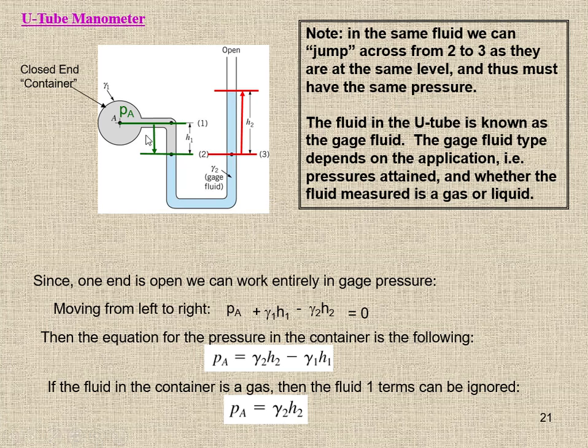The other way, we set the pressure of this side equal to the pressure of the other side. The pressure here and here is the same, so there is no use including the height of the column of this fluid, because it is a continuous fluid at the same level, so both cancel each other. Now we are going to do the first way.